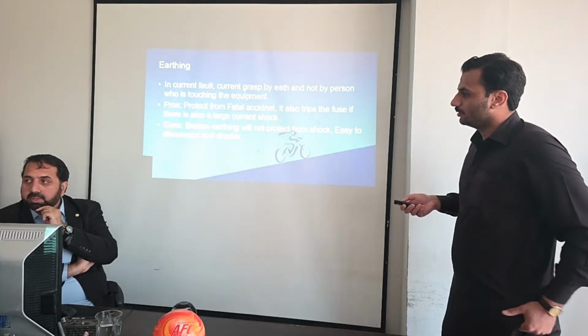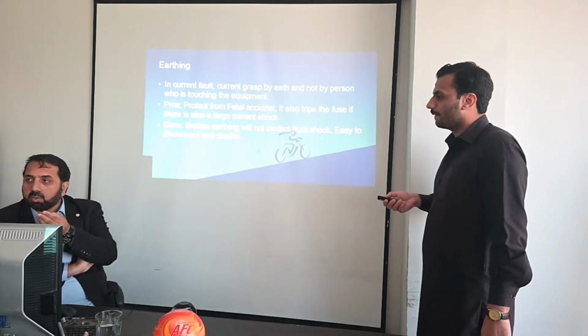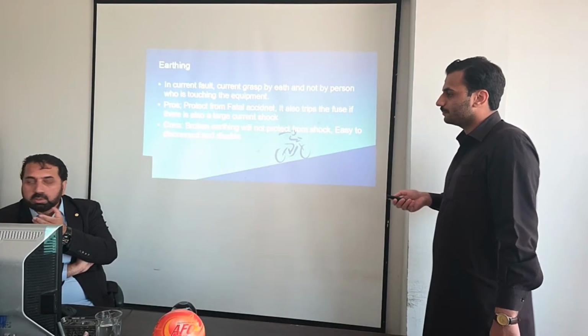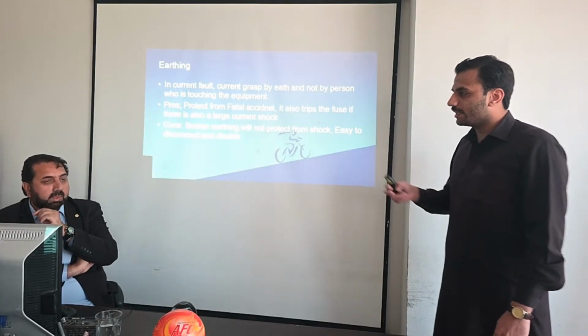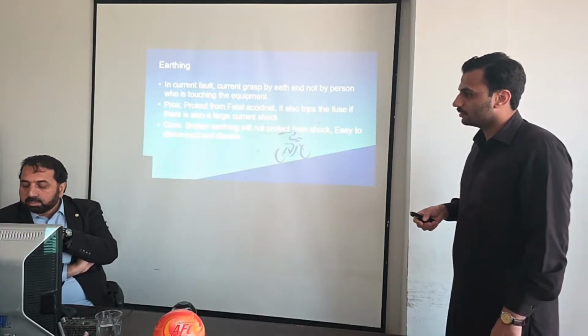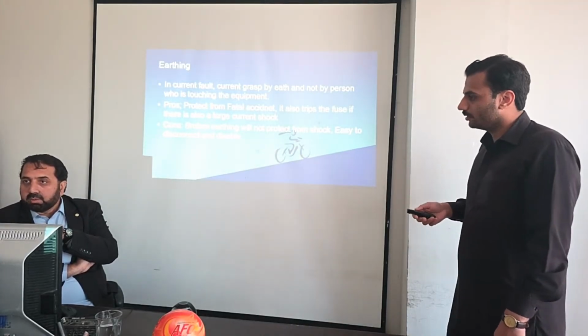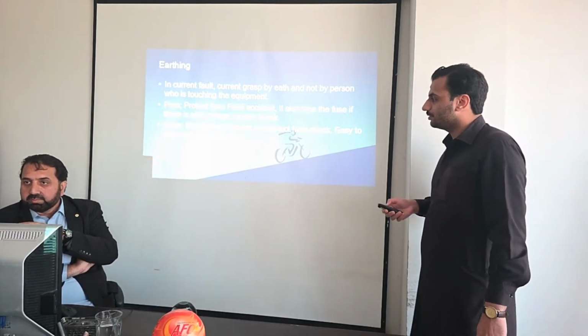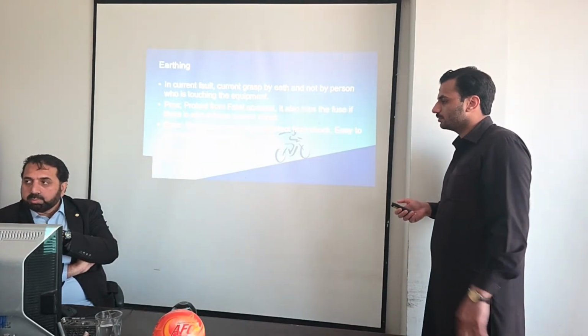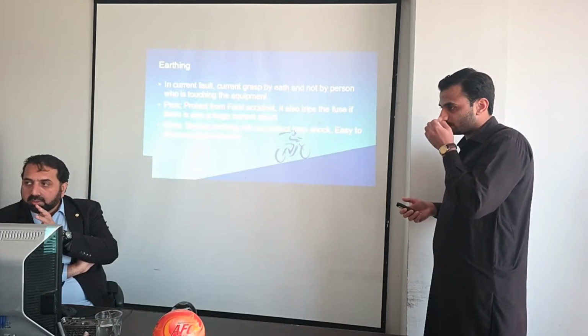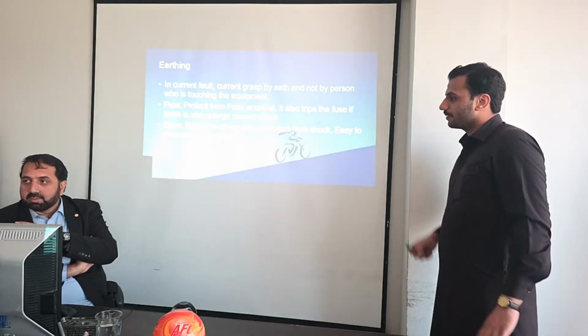Because it is properly installed. And you know how to make an earth system? Yes. How can we make an earth system? We use two rods and then we connect them with a wire. First of all, boring. Drill a bore of about 15 to 20 feet by boring machine.